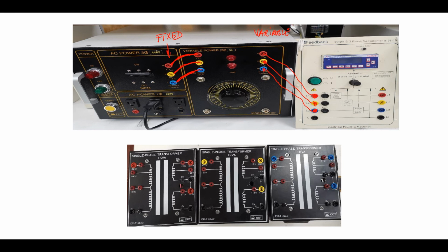Okay, and now before going to the other side, I will connect our transformer. We'll take this rated voltage here. So we'll take the whole winding for this single phase transformer, and this forms our Y to Y connection, Y in the primary. So this primary with this primary of this transformer, this primary with this primary side of the last transformer. Same thing we have to do for the secondary side.